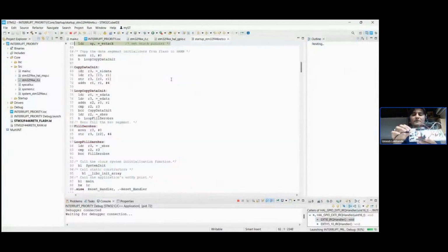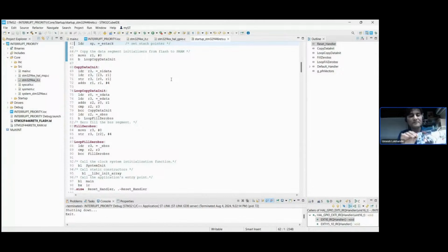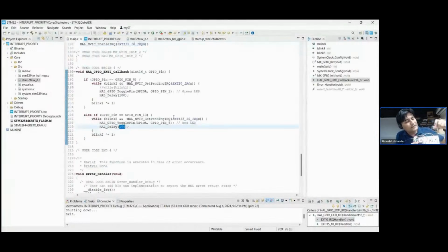So you can see this RGB LED is blinking. It's changing its color. And I think now the code execution is done, so the code is uploaded. So let me show you again to prove the logic that we spoke about, right? Let me press the EXTI0 button. That's the PA0 pin, that's where the switch is connected to.